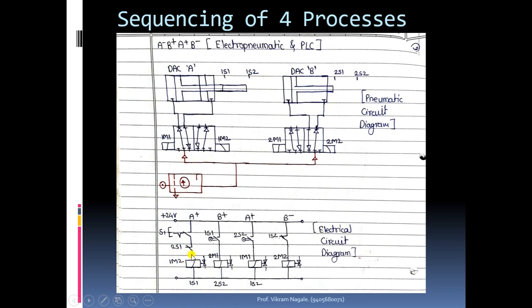Okay, so here everything is connected, only this contact is open, because of which the line is open. So after placing this S1 switch and keeping it in press condition only, what will happen? The supply will be given to 1M2 coil, and the retraction process will start. So retraction process will start means the rod end will try to move from 1s2 to 1s1, and during that, whenever this rod end leaves 1s2 position, 1s2 limit switch will get unpressed.